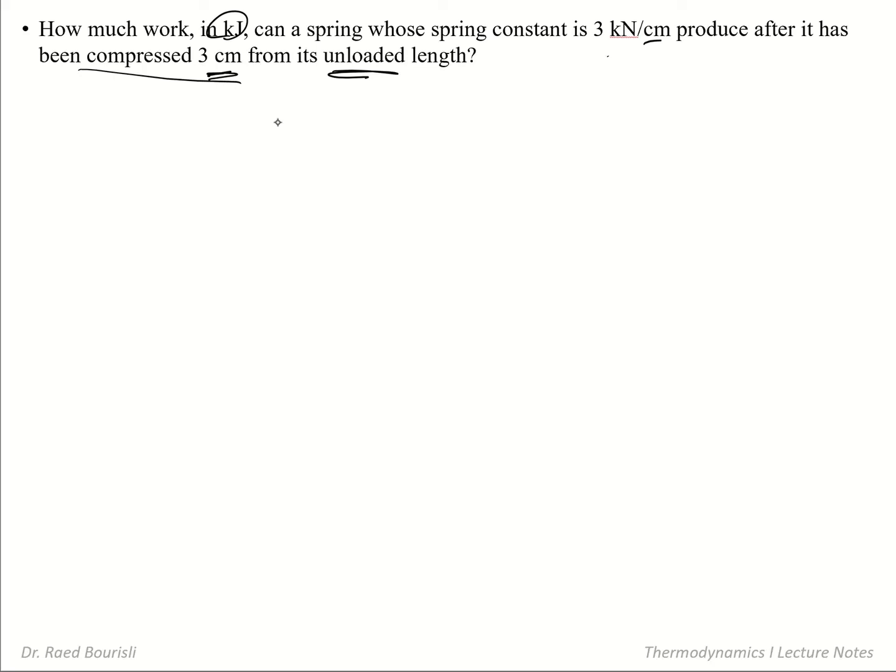It's asking me about the work. So we know that work for anything is the integral of F ds from state 1 to state 2, and for the spring F is equal to kx, the spring constant times displacement. So this is the integral from 1 to 2 of kx dx.